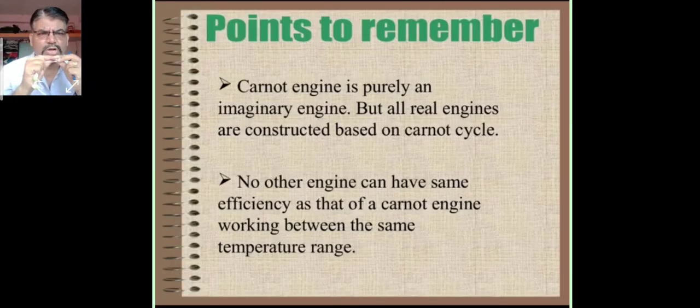Now what is the point to remember about the Carnot cycle? Carnot cycle is purely an imaginary cycle, but all real cycles, all the gas power cycles and the remaining vapor power cycles are constructed based on the Carnot cycle. Carnot cycle is one of the theoretical or ideal cycles, which has the highest efficiency, because there are two isothermal processes and two isentropic processes.